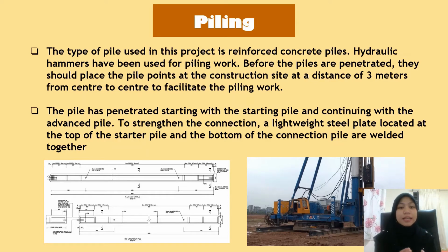The pile is penetrated starting with the starter pile and continuing with the advanced pile or extension pile. To strengthen the connection, a steel plate located at the top of the starter pile and the bottom of the connection pile are welded together.